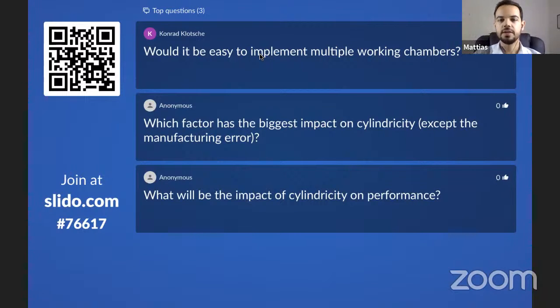Well, as we saw there, between those four factors we considered, there is a similar effect of the bolt pretension and of the Young modulus, the material properties of the block. But you have to consider in that case, as you saw from previous works, we didn't go deep into the details of how to model the screw threads. So it could be that this factor is really even more relevant. So there is this possibility.